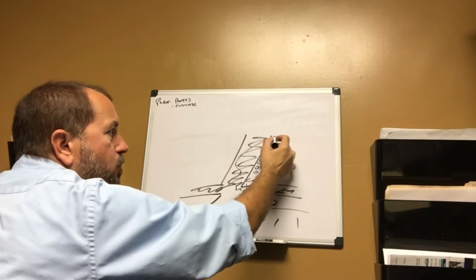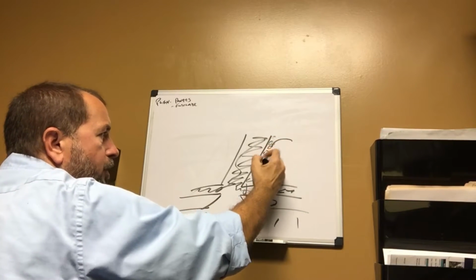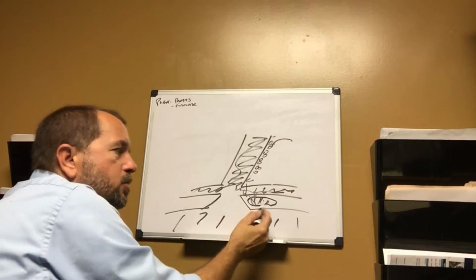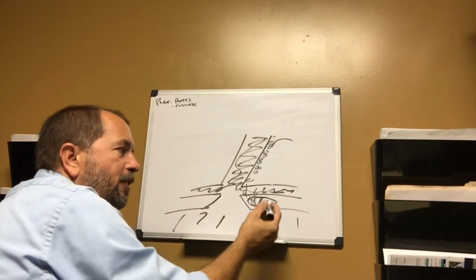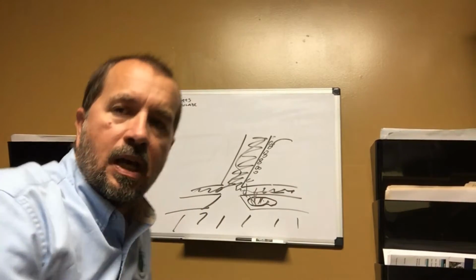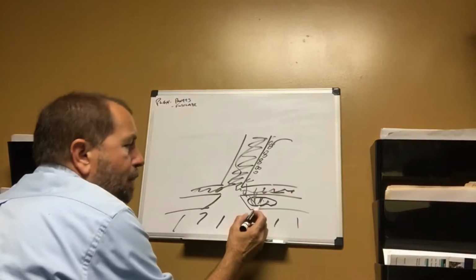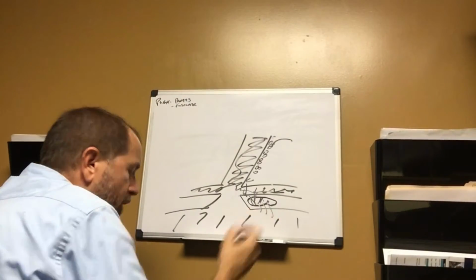So what's going to happen is we're going to collect all the water into the French drain, and it's going to move it into this rain garden, where the rain garden will fill up, and once it crests as much as the water it can hold, the balance of it is going to roll out into the street. We can't just take every bit of water that we have and drop it or pump and put it out into the street to make it the city's problem to pump it out. We're going to have to mitigate the water on our own property.